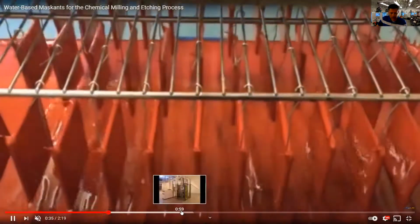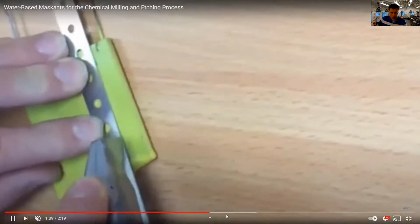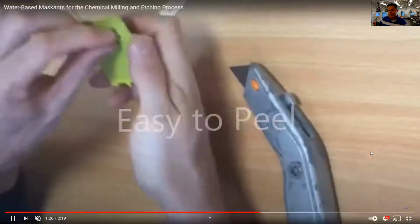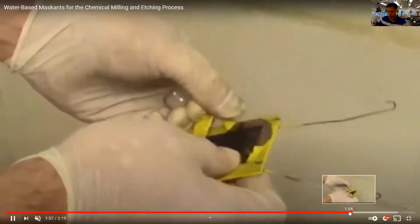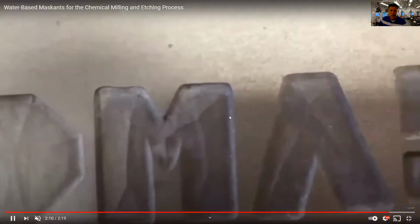Then you could either cut it off with a razor blade exactly where you want it, or you could use a laser to cut out the acid resist, which is a little bit more accurate. Then you literally just peel the resist off wherever you want to etch the part. And you can see right here, it etches the part down using that acid. So it's chemical milling.